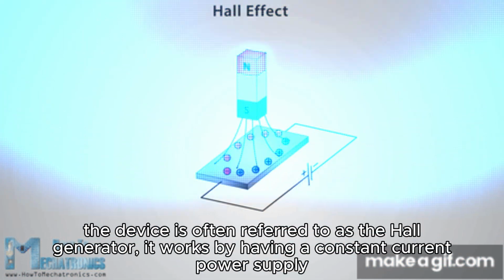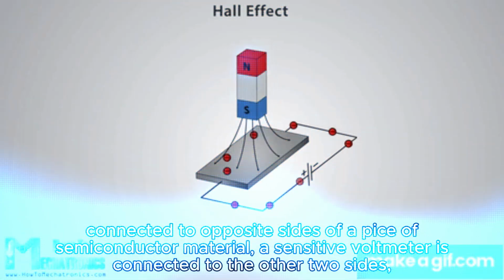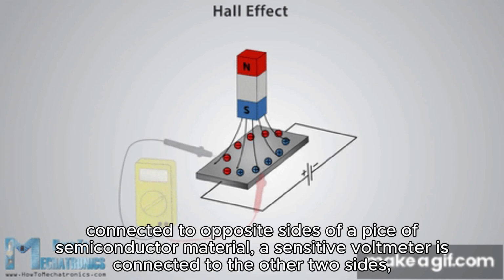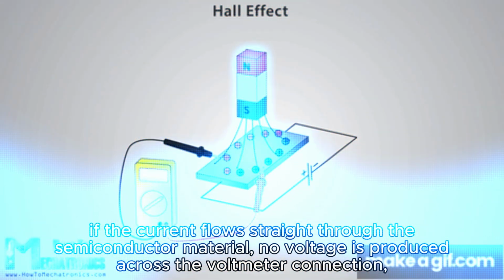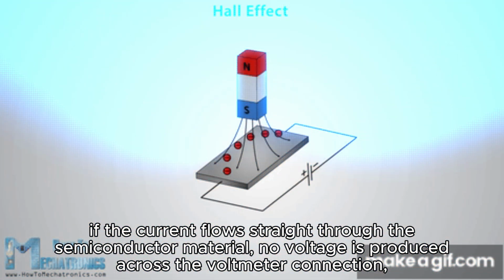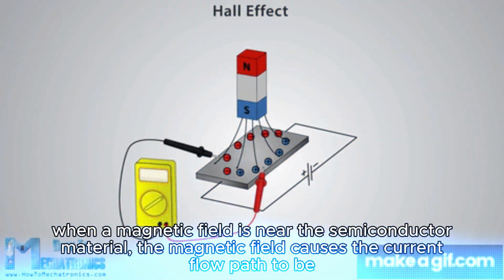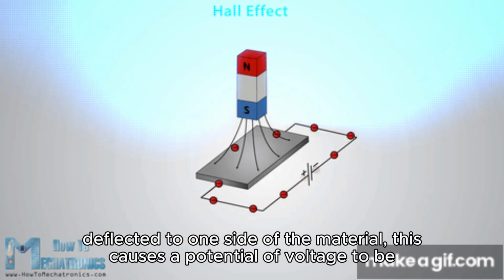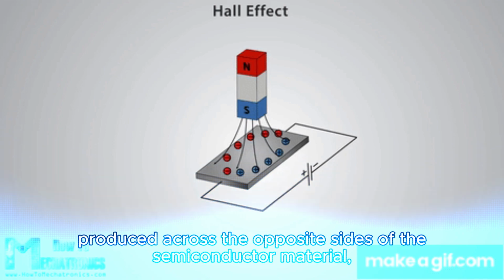The device is often referred to as the Hall generator. It works by having a constant current power supply connected to opposite sides of a piece of semiconductor material. A sensitive voltmeter is connected to the other two sides. If the current flows straight through the semiconductor material, no voltage is produced across the voltmeter connection. When a magnetic field is near the semiconductor material, the magnetic field causes the current flow path to be deflected to one side of the material. This causes a potential or voltage to be produced across the opposite sides of the semiconductor material.